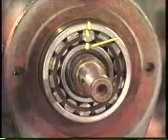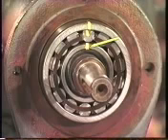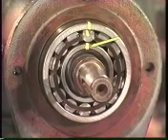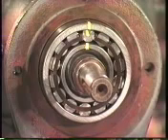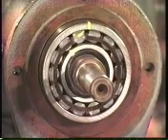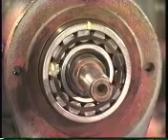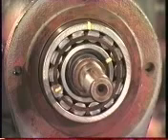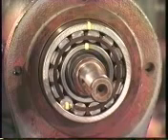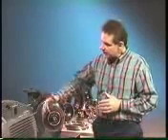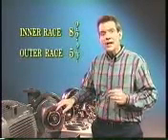The inner race frequency can be approximated in the same way as the outer race frequency. With the reference marks lined up again, we will assume a defect at the mark on the inner race. As the shaft is turned, let's count the number of balls that pass through the inner race defect. 1, 2, 3, 4, 5, 6, 7, 8, and a fraction. We see here that the inner race frequency is also non-synchronous. Notice that the inner race frequency is 8 and a fraction, whereas the outer race was 5 and a fraction.